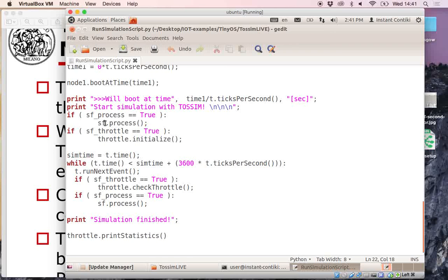You see here the simulation script is a little bit different because I have this new component, which is the throttle, which basically works like the simulation time in Kuja. You remember that you could set the simulation time to a certain percentage in order to respect real time. Well, this does basically the same thing. It forces the simulation to run at the speed you want it to, so we will see exactly one message per second here. So computer time is the same as real time.